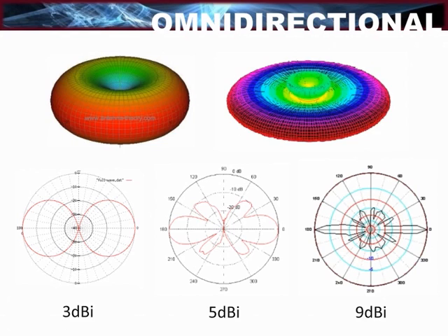The bottom right graph represents several antenna elements. It can be seen that the more elements that are added, the more elongated the primary lobe gets. This is effectively increasing the gain or the focus of the antenna.